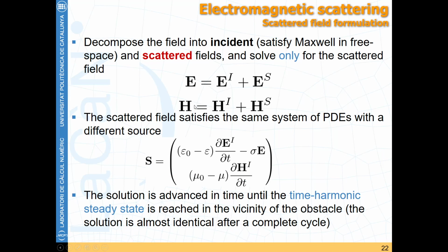So we know that E and H, the magnetic and electric fields, are the solution in the space where we are, with the material properties given by the permeability mu and the permittivity epsilon. In the empty space, the incident wave, assuming it is coming from the empty space, satisfies the same equations using epsilon sub 0 and mu sub 0. Because these quantities are known and we assume that we know the incident fields, what we have is a system of equations with an additional source term. We deduce where this comes from, which is just solving for the scattered field. So that's our unknown in the system.